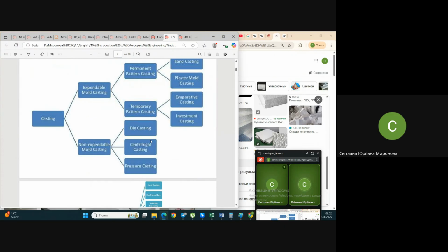So usually this die casting is very convenient, you don't need to produce these forms time by time, hundreds of times, like with expendable mold casting, when you have patterns that may be used to produce a form, a mold which you are going to use only once, and next it's destroyed after the casting process finishes.